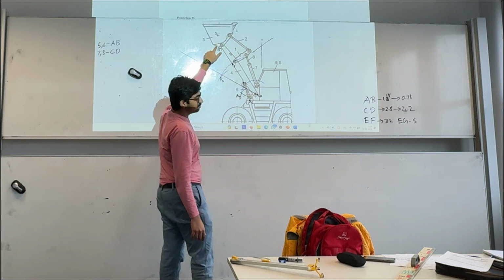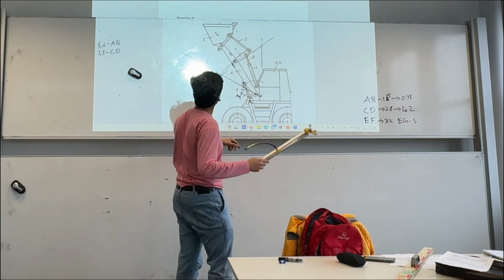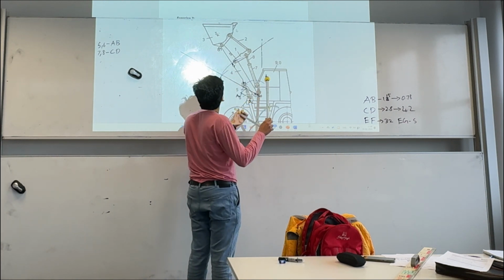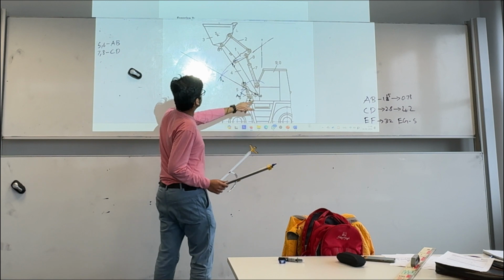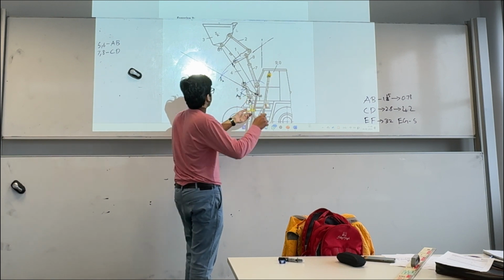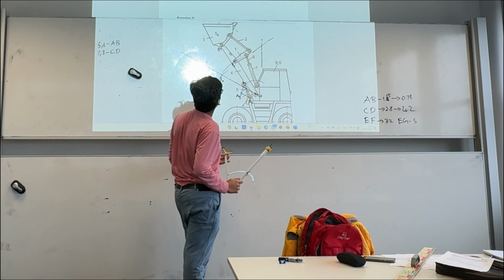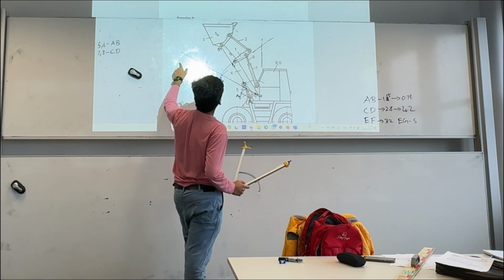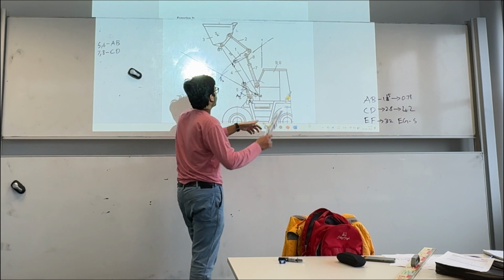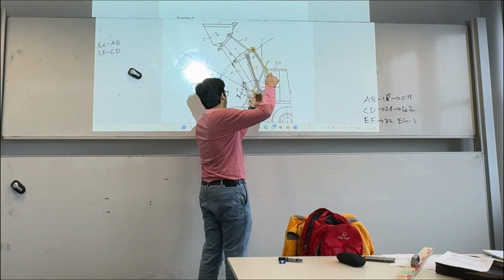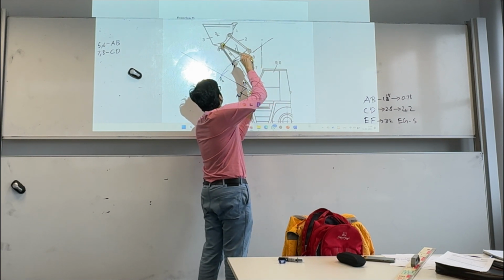Then I need to make the G point similarly. Again, 2 points of reference. E0 as reference, A0 as reference. No, not A0. I will use A2 as reference so that I get a new point and not the same point again. If I use A1 as a reference, I will basically get the current G position. Nothing would change.